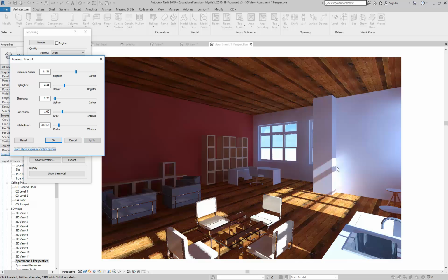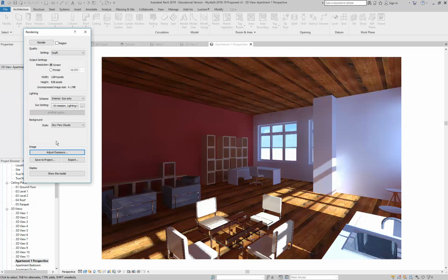But then as you start to reduce these overexposed areas where it's all white, you're going to get really dark areas where it doesn't receive enough light. And unfortunately in Revit there's no overrides for global illumination. In other words, you can't cheat and add in extra bounce lighting the way you can with lots of other rendering programs like V-Ray definitely, and Mental Ray could do that as well, which is the old one Revit used to use, but the new one called ART that Revit now uses doesn't give you that option. So to get more balanced lighting, we definitely want to have some artificial lights.